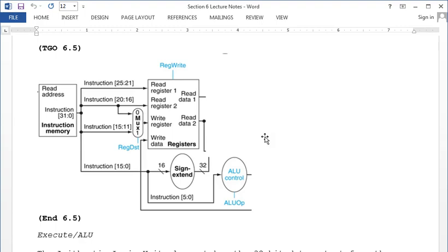What would I want to put there? I'm trying to have 64 bits. So I have a 32-bit value coming from read data 2. I have a 32-bit value here. And I want only one of them to go to the ALU. So I only want one 32-bit value. What would I use? Yeah, you'd use this. So it would be a 64 to 32 multiplexer, but you're correct. So it's 2 to 1. And you guys have already built that, right? So since it's going to be the second source to the ALU, the control signal that's going to control that multiplexer is called ALU source.